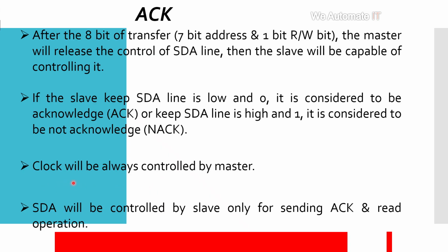Again, the clock will always be controlled by the master. There is no ambiguity in that. The SCL, that is the clock, will always be controlled by the master in the system. The SDA, meaning data transfer, will be controlled by the slave only for sending the acknowledgement and for read operations. So the slave uses SDA only for those.